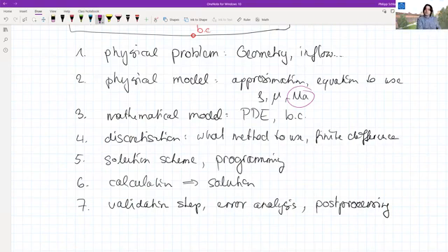But then I have done the solution, or I've calculated everything, I got the solution, and I realized my Mach number was actually 0.9. Then I guess it would come the point when you have to say, okay, maybe the choice of doing incompressible simulations was not a very good choice. I actually should have chosen a compressible simulation, or the compressible equations, for instance.